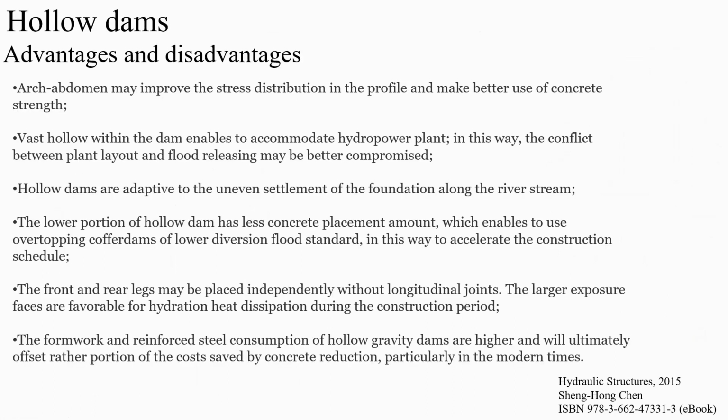In conclusion, the use of arch may improve the stress distribution. The concept of hollow dam is adaptive to the even settlement of the foundation. The lower portion of the dam has less concrete placement amount, which helps in accelerating the construction.